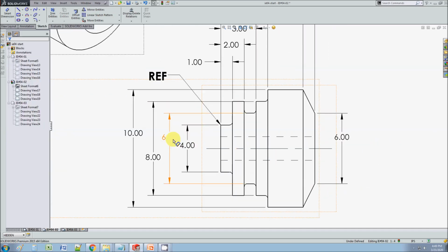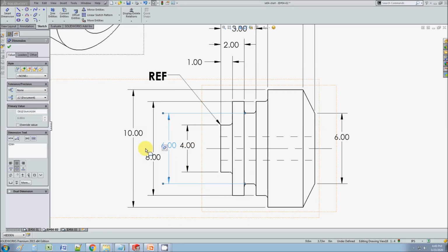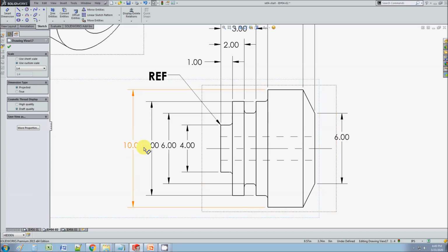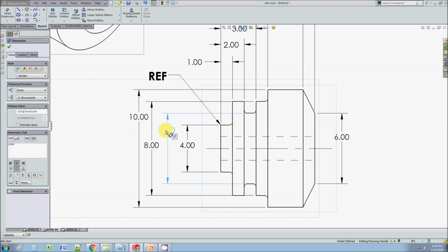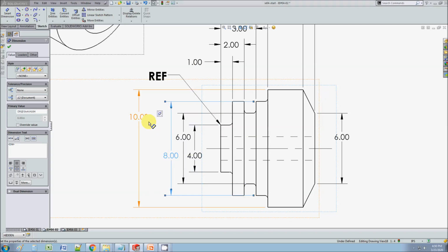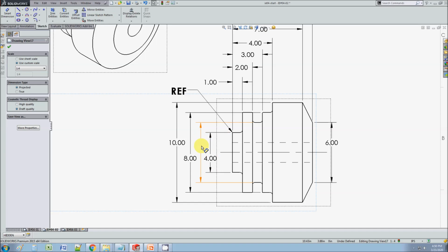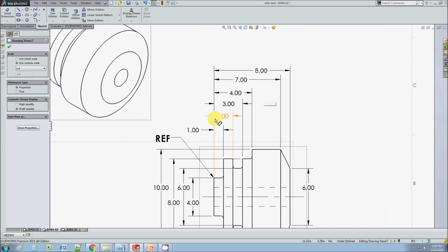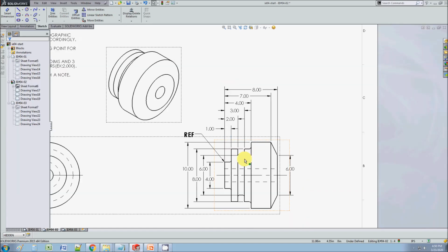So as you can see here, I did not do this, you see? Remember, we talked about that. We said this was confusing. I did not align the dimensions. I'm instead doing a zigzag, so I take advantage of the dead space, just like you see. Okay, so I've added a zigzag here, and then here I've added a staircase. Okay, so it's nicely spread out.